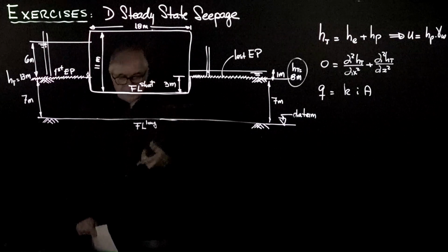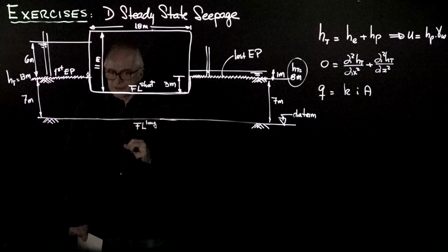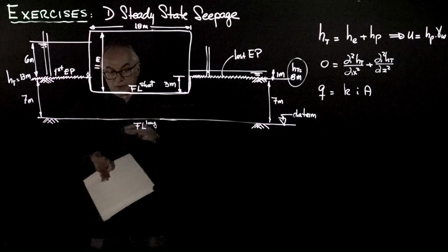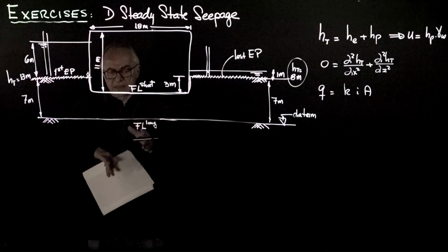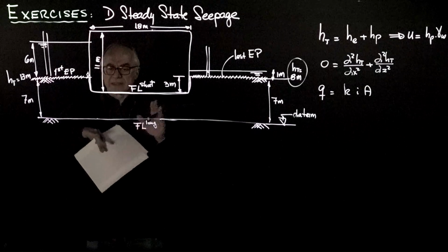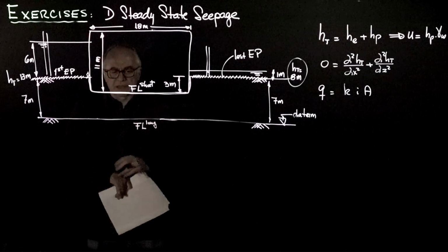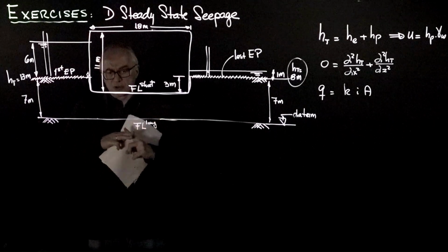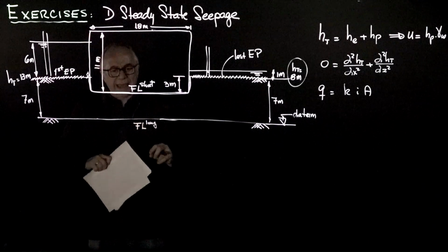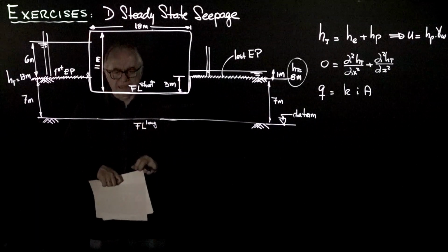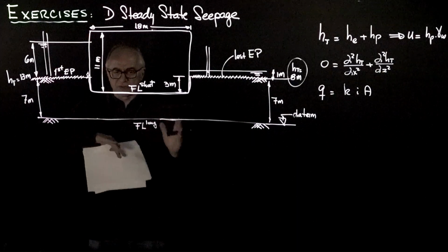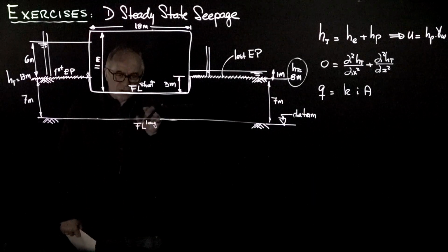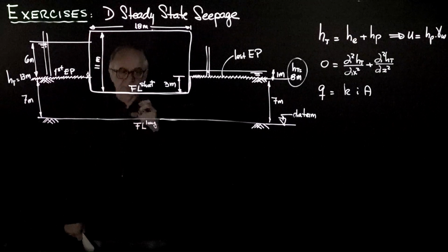The homework or the exercise requires that you do it first graphically. And so graphically, what we are going to do is draw flow lines and intermediate equipotential lines so that we satisfy Laplace's equation, and that requires that flow lines and equipotential lines intersect at normal conditions, normality. And in order to simplify the sketching and the analysis, we want to form, between consecutive flow lines and parallel equipotentials, squares, or geometry such that a circle would touch all the boundaries.